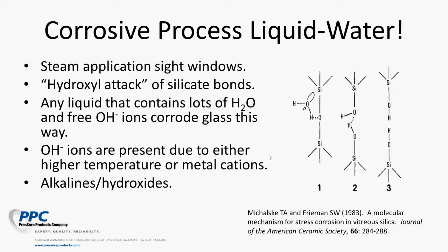The fact that water eats away at glass became really obvious at the beginning of the Industrial Revolution. Back then, steam engines were the only game in town, and they boiled water under pressure. They used expansion pistons or turbines to convert thermal energy into mechanical energy. For those, it was very important to make sure that the boiler had the right amount of liquid water. So these engines had sight glasses, and these sight glasses etched away right at the seals. Of course, that leaked, and when the leaks couldn't be resealed because too much glass had been lost, the whole sight glass had to be replaced.